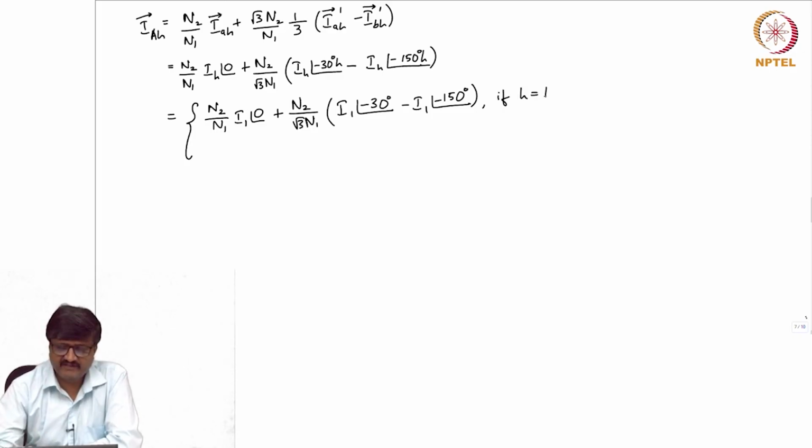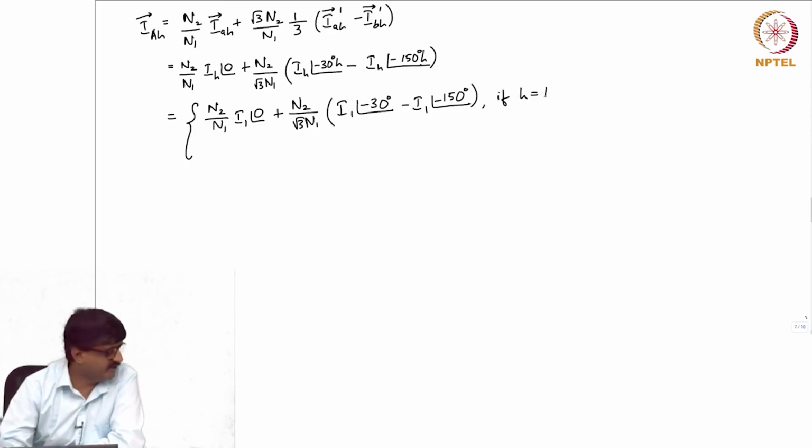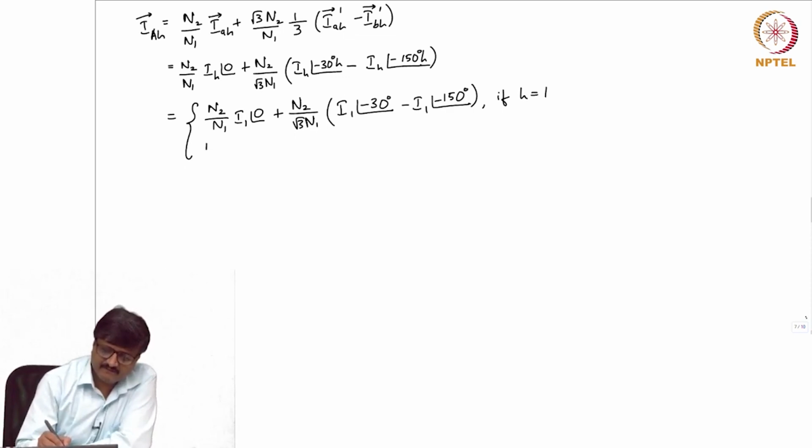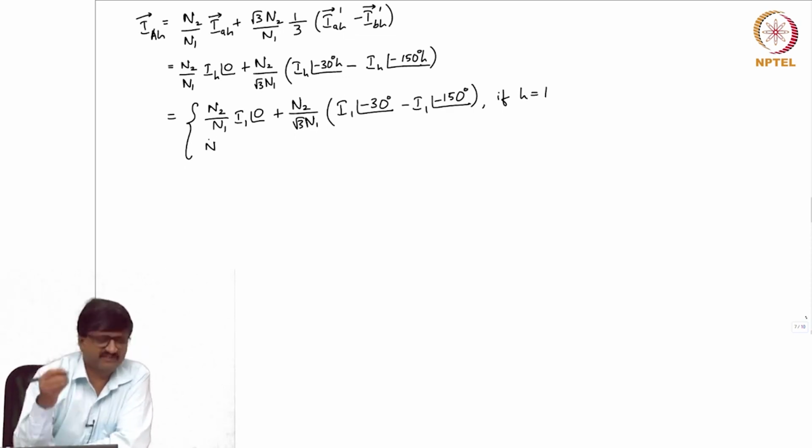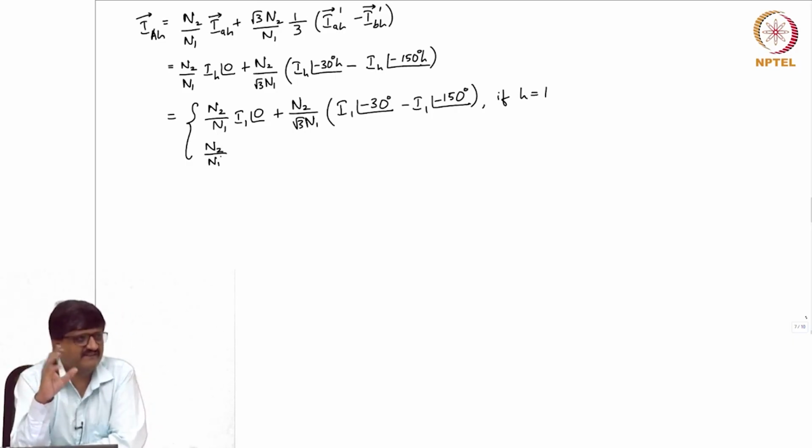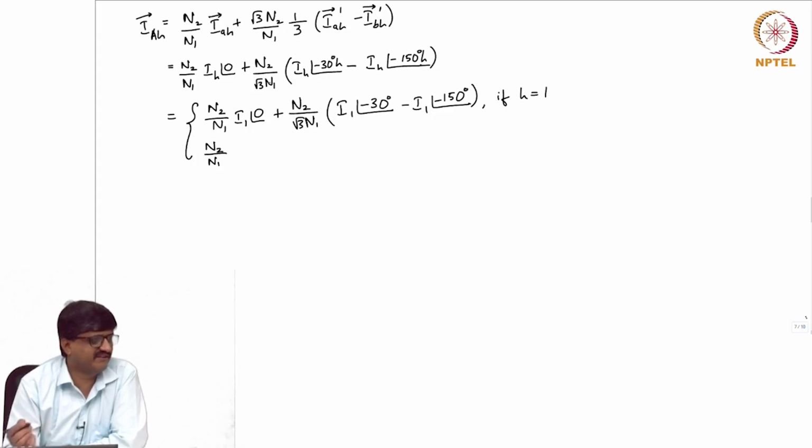H can also take the values of the harmonic component orders. So in that case H is equal to 6k plus minus 1. Now, I will replace this H by 6k plus minus 1 only in the phase angles, not in the subscripts for the current magnitude, it is not necessary.